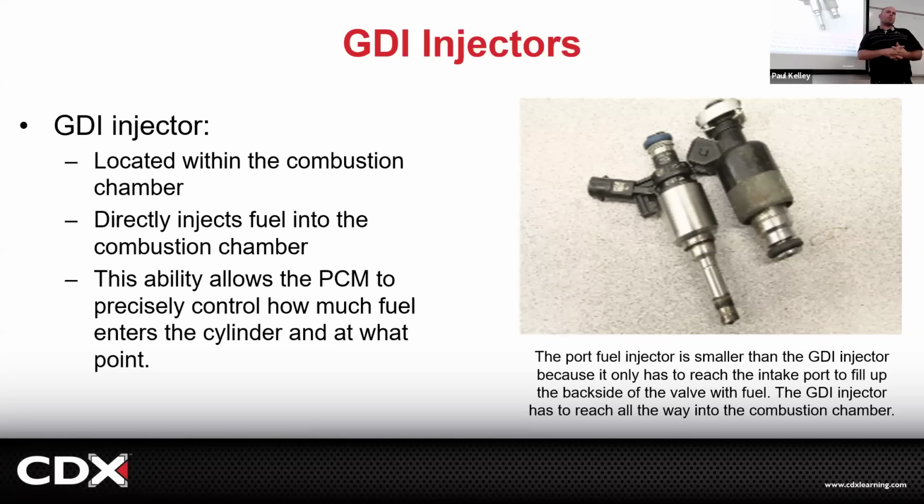And then I was like, hey, do you want to do 4 or do you want to do 8? He's like, how much? I said, well, the labor is not that much more to do the other bank because I already got the intake off. So I ended up doing 8 injectors on that, totally hooked it up. Quite a few people have found that video helpful. So this Teflon seal down here on a GDI injector can cause compression loss. Never used to be that way with port fuel.